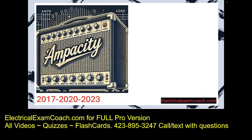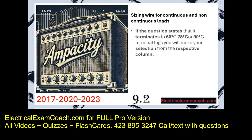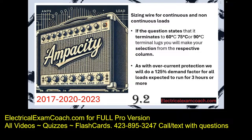I am the Electrical Code Coach from electricalexamcoach.com, and this is lesson 9.2 in our video series. In this lesson, we're going to be sizing wire for continuous and non-continuous loads. Let's recap on the basics before we get started. If the question states that it terminates to 60, 75, or 90 degree C terminals, we're going to make our selection from that respective column under normal circumstances. And the second one is, as with overcurrent protection, like we learned before, we're going to do 125% demand factor for all loads that are expected to run for 3 or more hours.